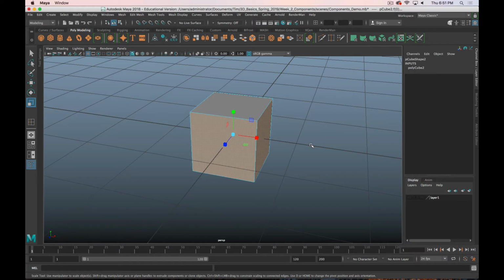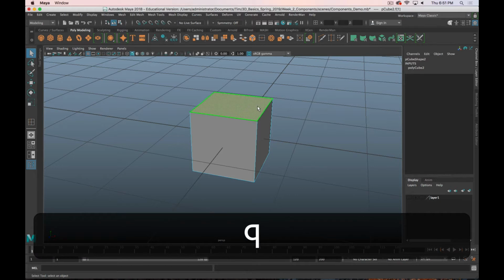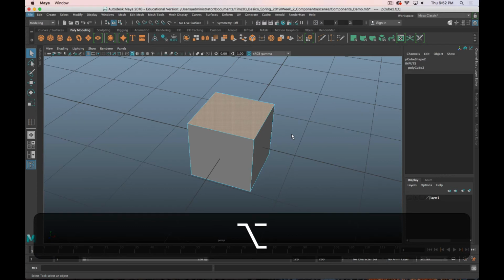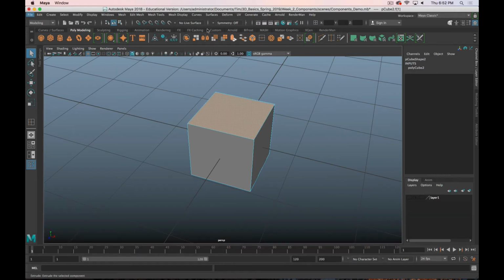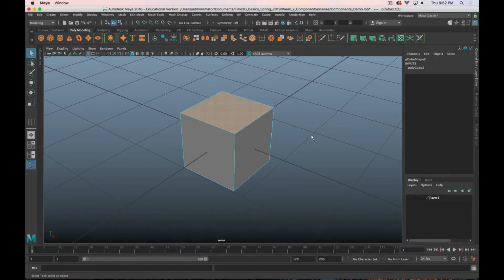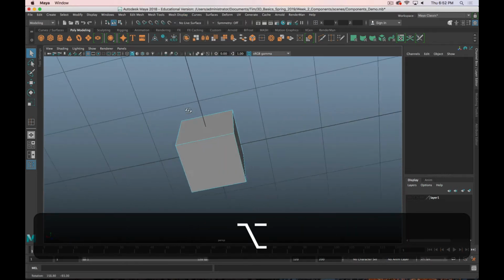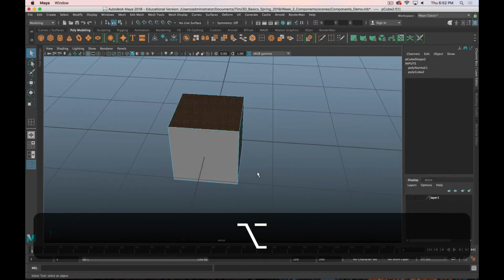I talked about this a little bit earlier, but I want to have it recorded as well. Faces have a property called normals, and normals refer to the direction that the face is facing, or the front side of the face. By default, on any primitives, the normals will be pointing out. But there are various combinations of actions that will cause the normals to be flipped or reversed. If that happens, it will look like this. You'll just have one face that is completely black, and it will be confusing as to why. It just means that the face is pointing the wrong way.